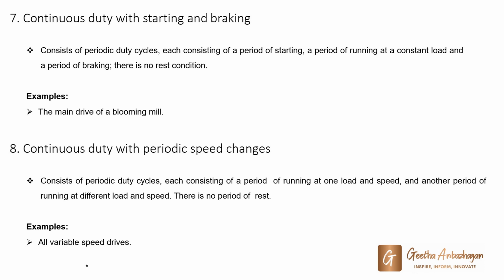And finally, we have continuous duty with periodic speed changes. It consists of a period of running with a load at a particular speed and a period of running with a different load at a different speed, which are not enough to reach their respective steady state temperature. Further, there is no period of rest. This type of duty can be accomplished by single phase or three phase induction motors and DC series motors in traction.